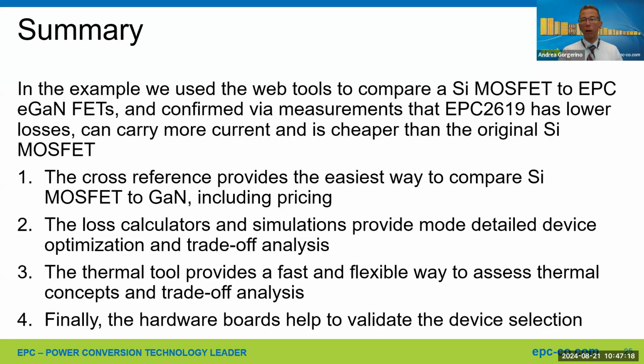By the way, when you do it that way, it also has a lot of interesting advantages. We don't have time to go into detail here, but because now you have more levels, you have more freedom in the modulation techniques, which means you can actually reduce the voltage steps on the output. And when you use an inductor as an output, or any load for that matter, that volt-second reduction can have a lot of benefits. It's almost like a switching frequency enhancement. So even that topology, on top of having very good low voltage devices that can be used for higher voltage applications, has some inherent topology-level advantages, which are really interesting. And we have a couple of examples of that on our website.